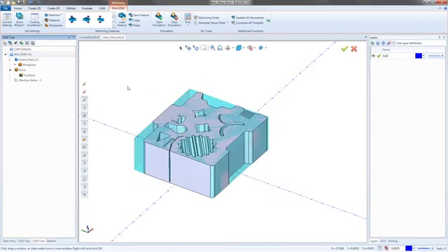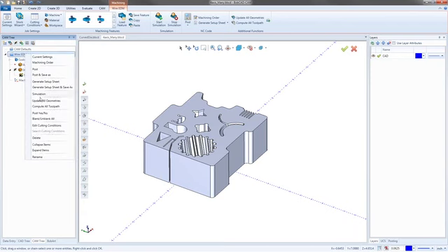So this is not something I usually mess around with. I don't have all the settings that I need to make a Mark 21, all the new settings that I need for the Mark 21. But with the help of a manual, or if I could get a hold of one of the guys at Sodick, we could probably put together the database a little bit better, or at least add more of the materials that I might be cutting to that database.